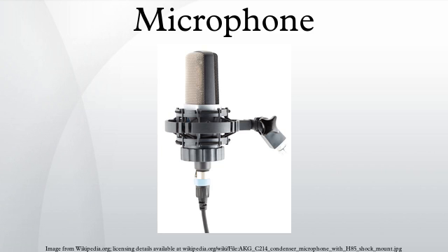All microphone calibration is ultimately traceable to primary standards at a national measurement institute such as NPL in the UK, PTB in Germany and NIST in the United States, which most commonly calibrate using the reciprocity primary standard. Measurement microphones calibrated using this method can then be used to calibrate other microphones using comparison calibration techniques.